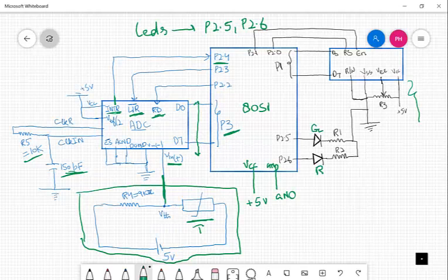Then this data will be actually analyzed, and using the formula we have discussed above, this data will be changed to exact temperature, and depending upon in which range this temperature rises, green or red LEDs will be either turned on or off, and also this temperature will be written on the LCD, and also there will be a special message in the second line of the LCD that will actually tell us about the state of the machine, how hot or how cold it is.